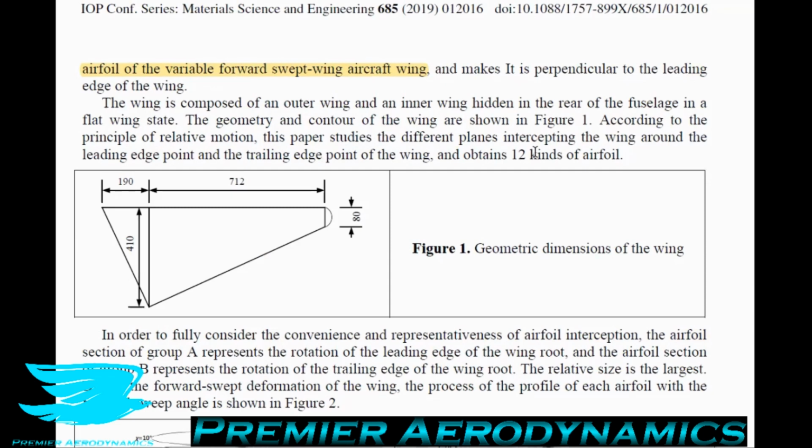And the problem with thin airfoils is they often have a fairly dramatic stall profile, and also they usually don't produce as much lift as thicker airfoils. However, at high speeds, they do become better in terms of their lower drag. So there's a trade-off here. In this particular case, we're not looking at very high Mach numbers, so an NACA 0006 is quite thin, but